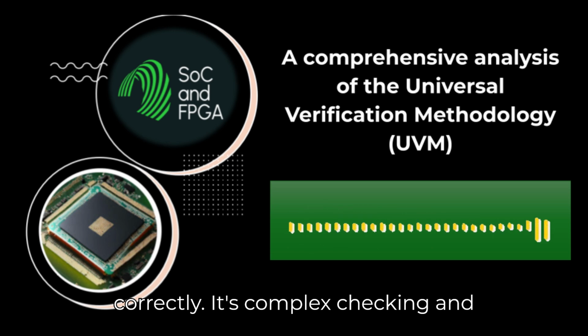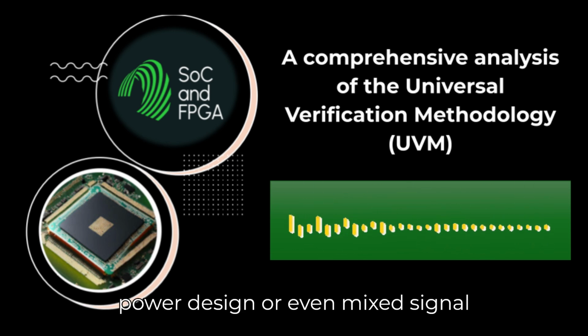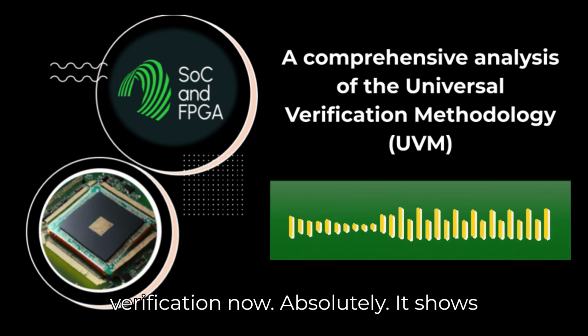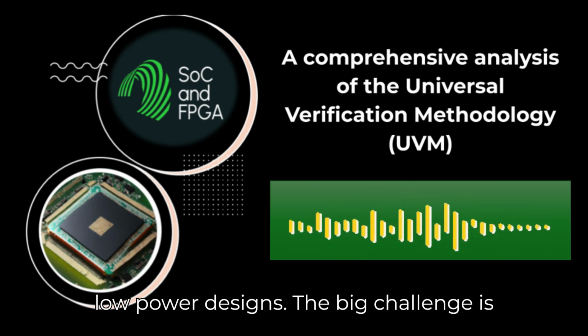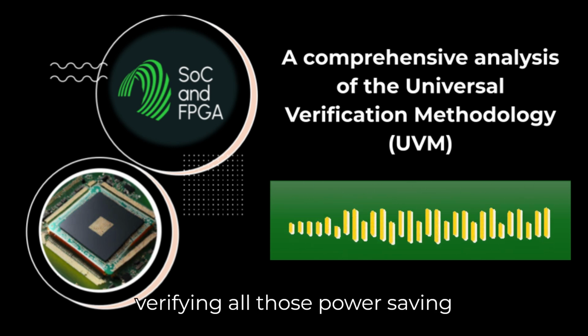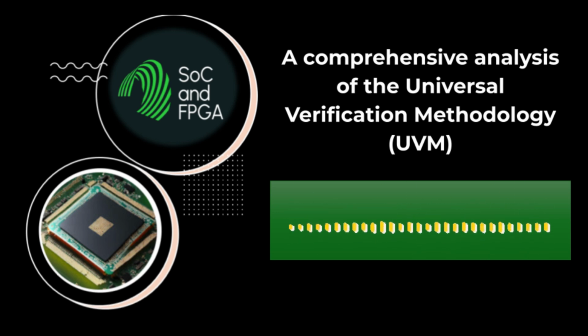It's complex checking. And UVM seems pretty adaptable, too. You hear about it being used in areas like low-power design or even mixed-signal verification now. Absolutely. It shows the flexibility of the methodology. For low-power designs, the big challenge is verifying all those power-saving features: power gating, clock gating, dynamic voltage and frequency scaling, DVFS.